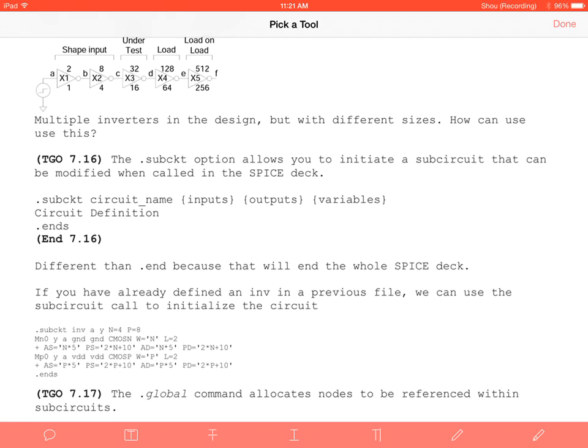If you're doing things with thousands and millions of transistors, and they all go to the same technology file, and you're using design automation, instead of having to rewrite the circuit definition over and over and over again, you can just use your subcircuit and include smaller files. And this is when you build cells, this becomes very important and useful.